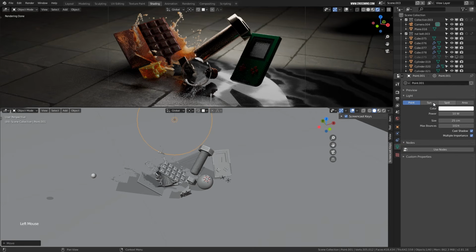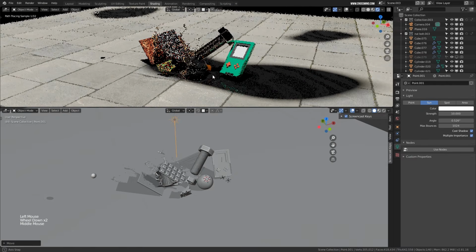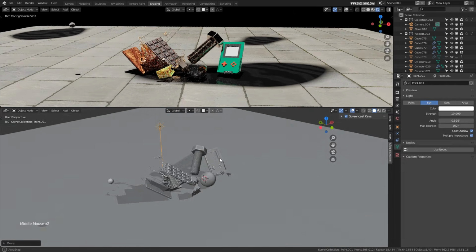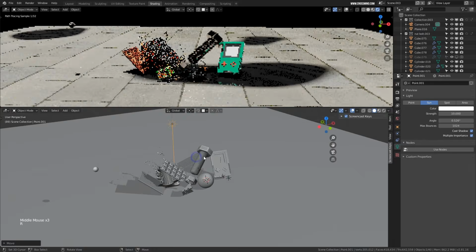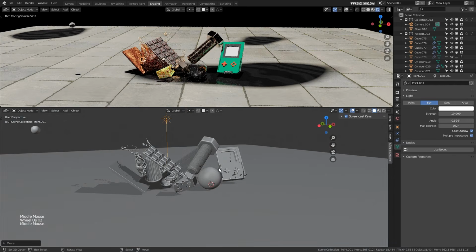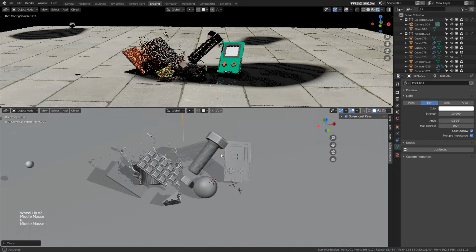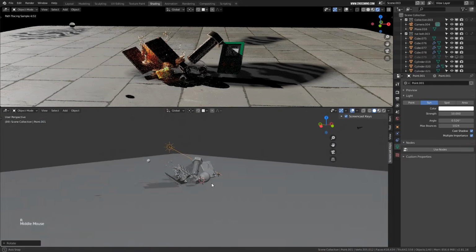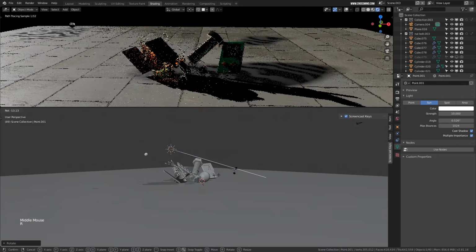And from here you can change the kind of light you want instead of deleting this one and creating a new one. So I'll change this to sun. Okay, now you'll see my entire scene is illuminated. The range of the light is actually limitless. And in this case, it doesn't matter where I position the sun, only the rotation will change the effect of the light. Okay, let's say if I tilt this to something like a sundown.